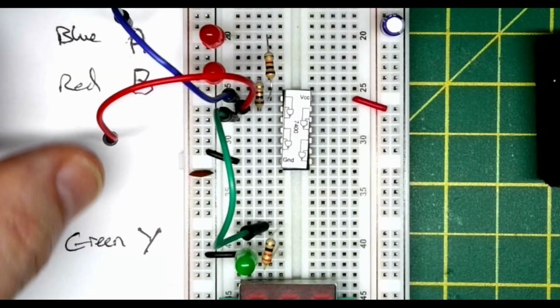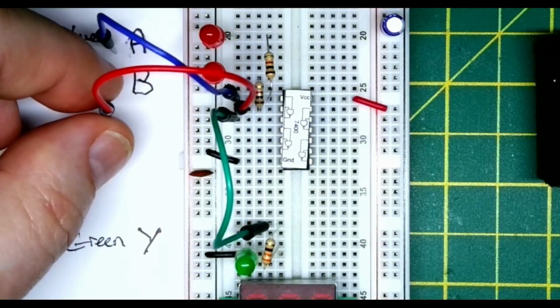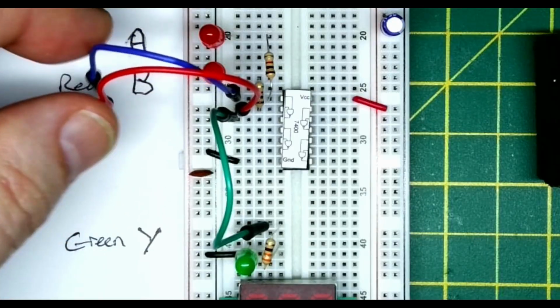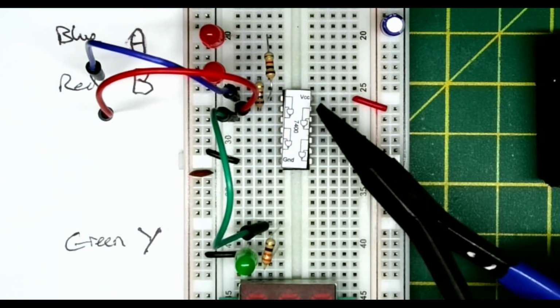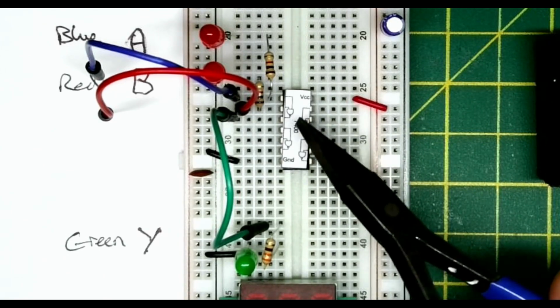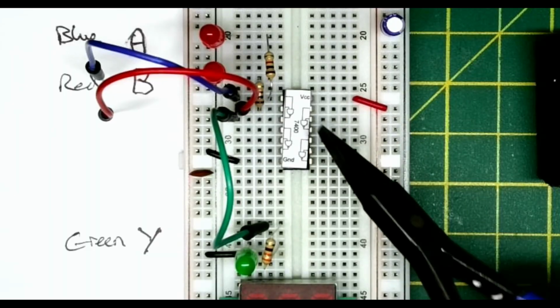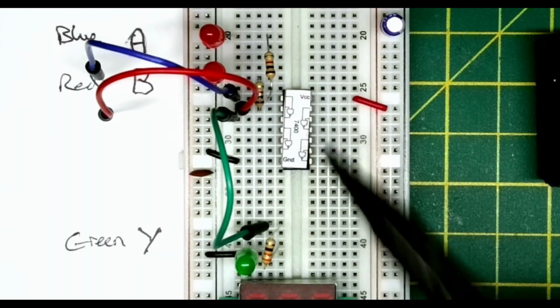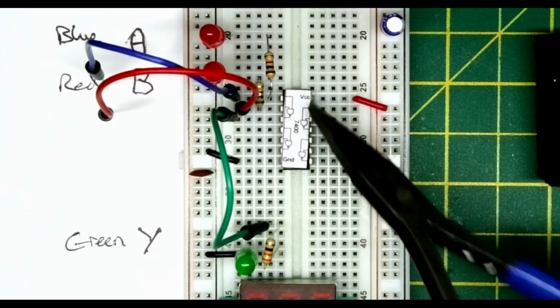So you can see that we've got 2 wires for A and B. A is blue, B is red. At the moment, they're just loose and free. Now, if you remember in the previous video, TTL inputs tend to have an internal pull-up resistor. So if we don't have anything connected to it, it will tend to default to high. Now in the AND gate, 2 highs would result in the output coming on. But in this case, when we get 2 highs, we in fact get a 0.